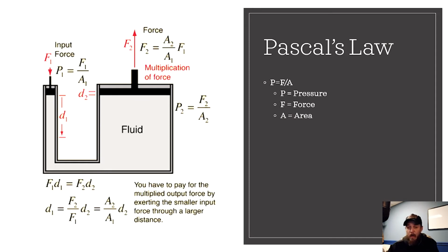So generally, we know what pressure we're going to want, and we can calculate our force or our area. Most of the time, we don't even have that information, at least in an automotive aspect. Medium duty, heavy duty, off-road, a lot of times we do have that spec and we can calculate that. But what we need to know is, much like Ohm's law, as we have any one variable, we can figure out the other two.